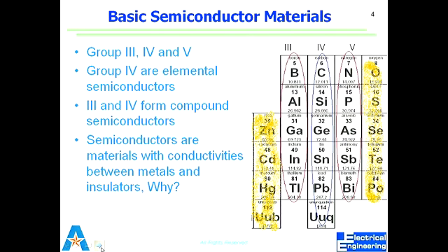Well, how do we define forward bias? It's how we bias the diode. So it's supposed to be the voltage source. What is forward bias? Positive terminal goes to P type, negative goes to N type.